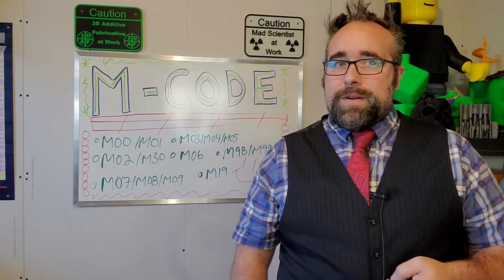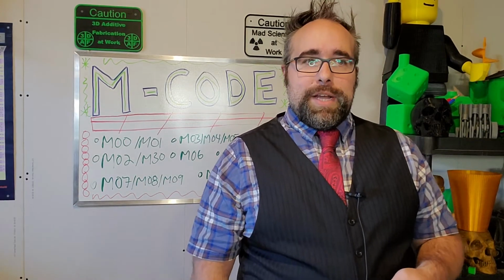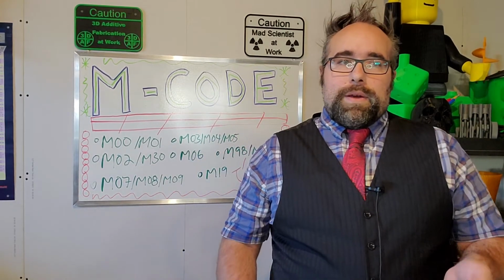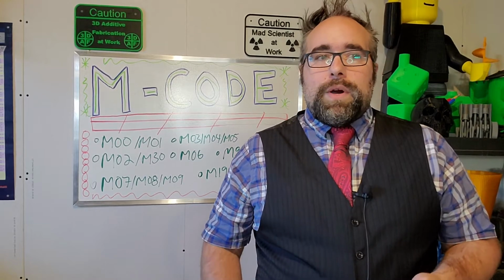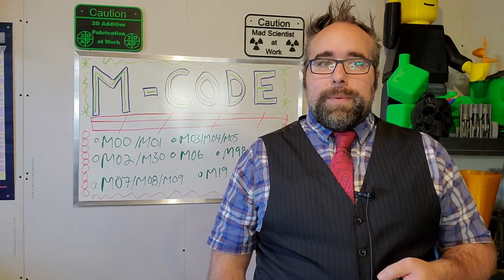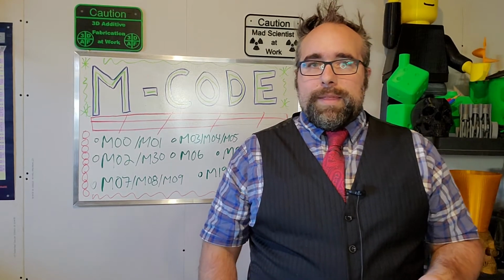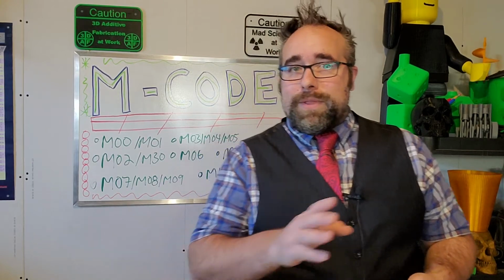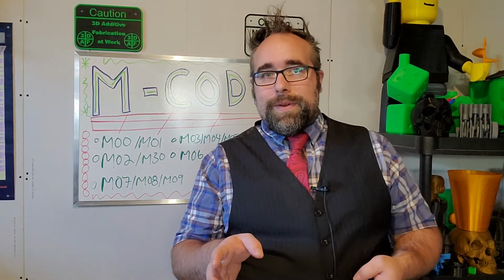And now my personal favorite, automatic tool change, M06. M06 is used for automatic tool change. It is used in conjunction with the T word for tool number, which indicates the tool that's being requested. Now, fun story, there's a lot of debate about this. Do you put the tool number or the M06 first? What I found in most controllers is that it doesn't matter, and either way, the controller will figure it out. But I'm still a personal fan of putting my T number first. Let me know in the comments how you feel about it.